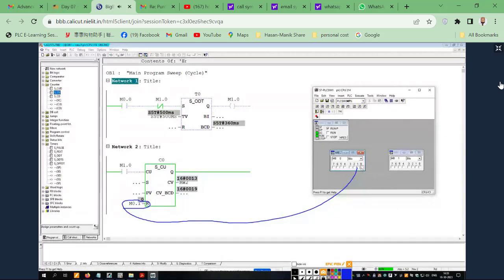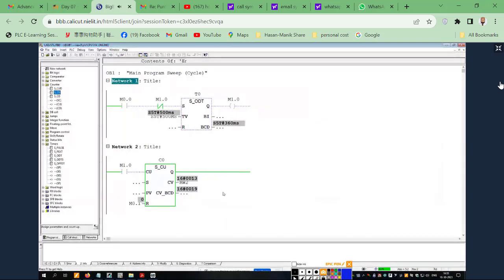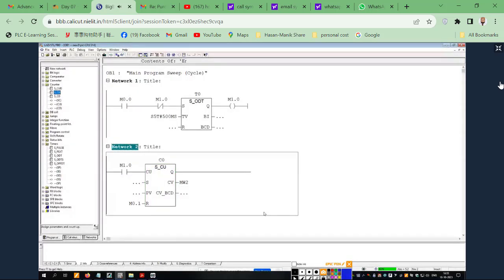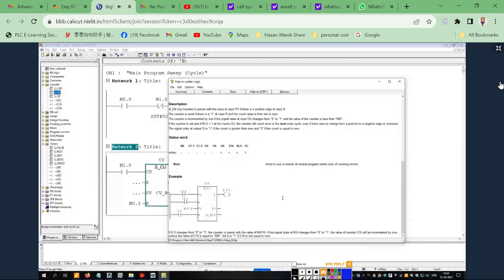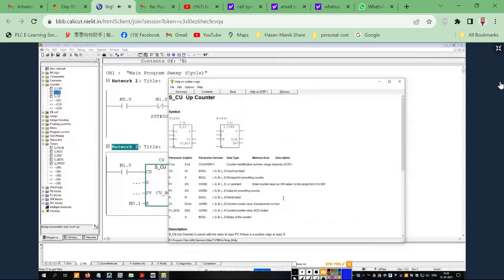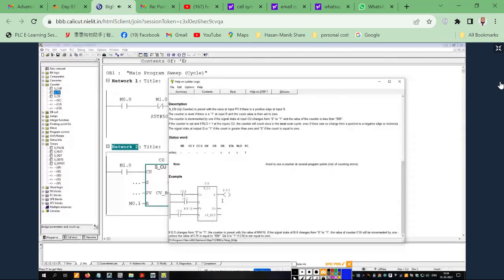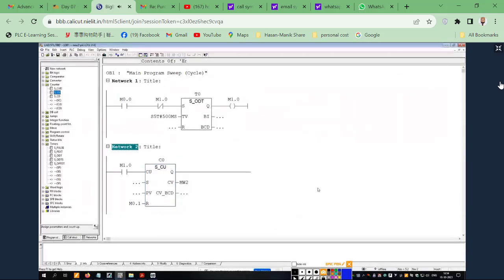Like this. So here normally the value you are getting is the normal integer value, then compare the value. Go offline. Okay, compare this value. If you want help, just select the instruction and press F1. This is the count value, input address, everything is available. Just press F1, all the data you are getting. Then you'll go for comparison, compare the value, and automatically you can reset.